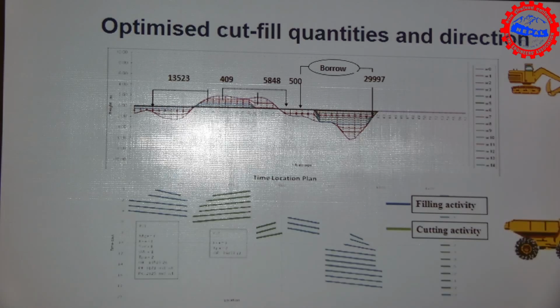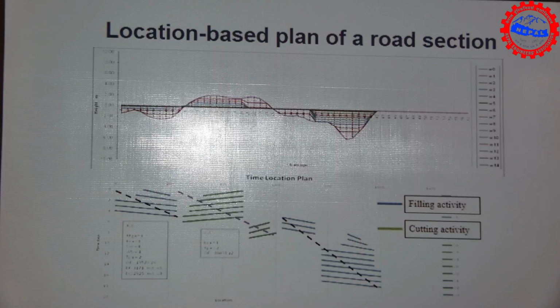This is one of the tools that can help you generate kilometer after kilometer, take different sections and give you a different understanding. If you look at the bottom line, this is all about the line of the location, chainage to chainage. If you're working at the beginning, this space is long. If you're going faster and faster, week by week, they're going to increase on that line. So by the number of weeks, you can easily count in what locations the work is going to happen, and what type of equipment and set of resources, everything allocated through the program. You don't need to do the programming, you just need to input the variables, and you can get all those allocated plans created, and that is called location based.